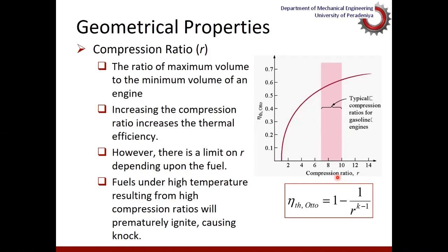In a vertical engine, when the piston is at the topmost position, there is a small gap. That gap is the clearance volume. When the piston is at the bottom dead center, at the far below position, the maximum volume is the displaced volume, the amount the piston displaced, plus the small space at the top, that is the clearance volume.